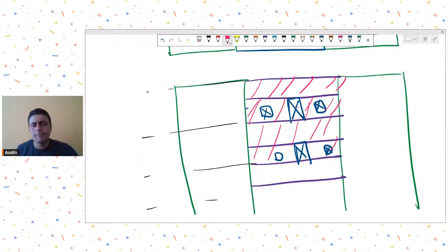Of course, that is quite time consuming, and because of so many shell elements, it will slow down your model analysis time also. So either you do this or you forget about this and just model it as a single line element like this.